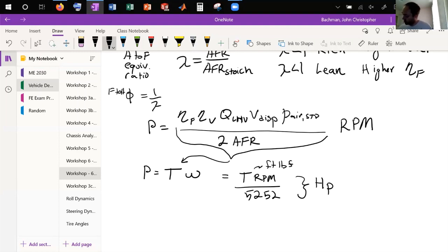So how do you improve this stuff? For your fuel efficiency, you want to get your compression ratio as high as possible. That'll help your fuel efficiency; those are directly related. Of course, you can get bigger displaced volumes, which is good. You want better intake and exhaust design, as well as better valving and timing of your valves. All that stuff is important. Even the shape of your piston will affect it. And your air fuel ratio, you can't really mess with much.